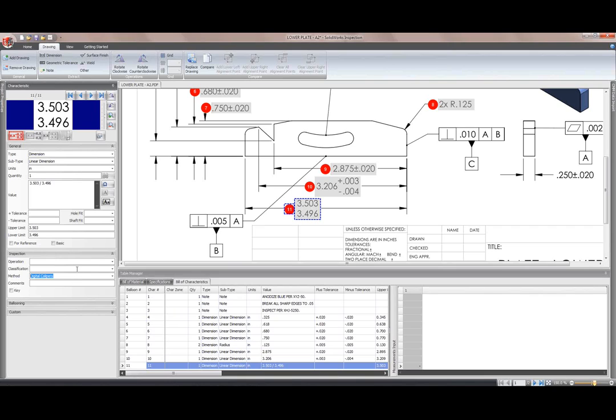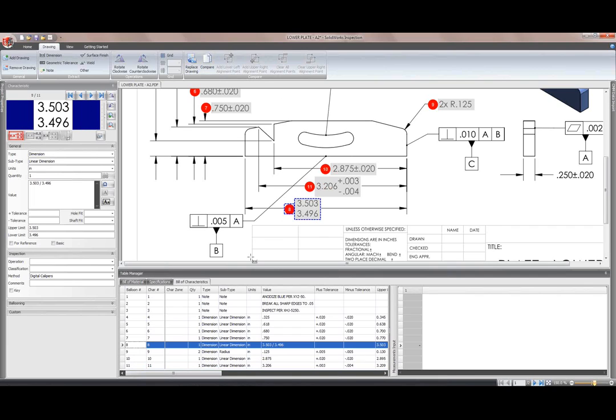So that's an option per dimension, or we can do that overall. We can move these balloons around. Currently they're in the order we picked them, but if we wanted number 11 to be further up somewhere and replace that with number 8, it just reorders all the balloons and puts number 8 at the end. So we just skip 8 out until we get to the end, so we can reorder them just as you'd expect to be able to do.